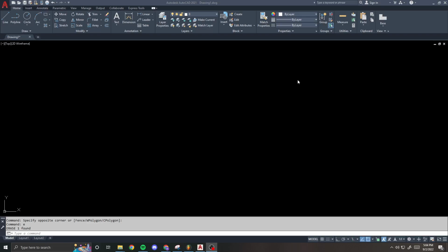Well, it's not a 3D dynamic block, it's a 2D, and it may not apply to everyone, but in my line of work, specifically with some of the companies that I've worked for, we do elevation views of foundation that show the rebar layout of a pedestal or an octagon or grade beam or something. And in those elevation views, those section cuts, we also show the anchor bolts. And the anchor bolts have a projection, they've got a total length, they've got one or two nuts on them, depending on what they're tying down. They've got a diameter.